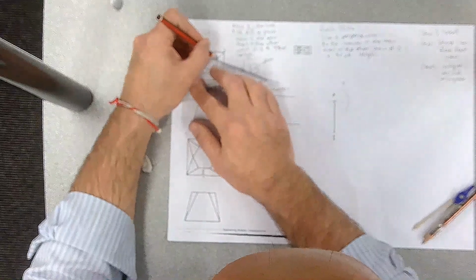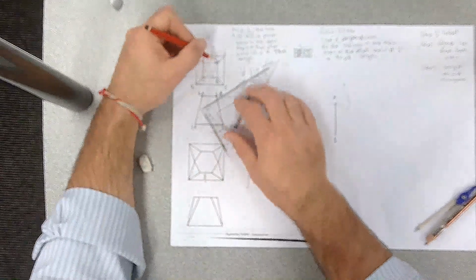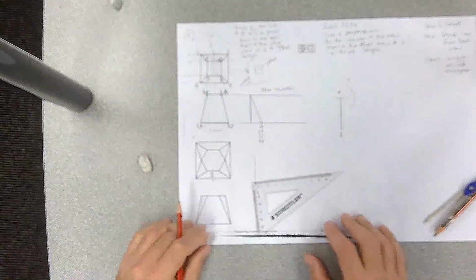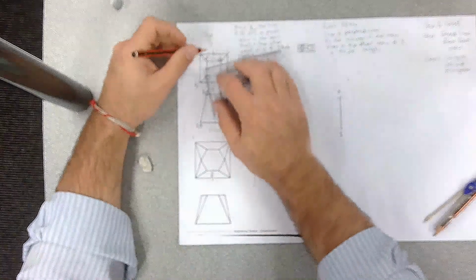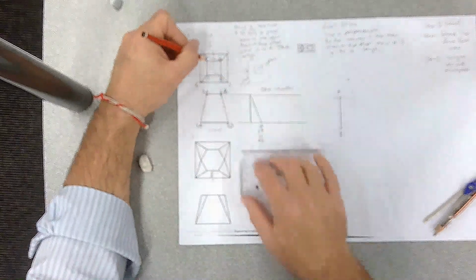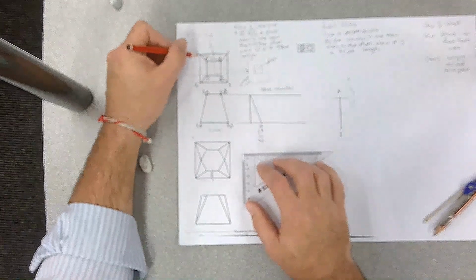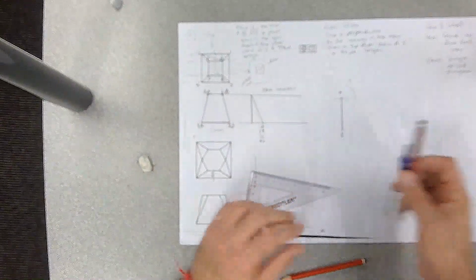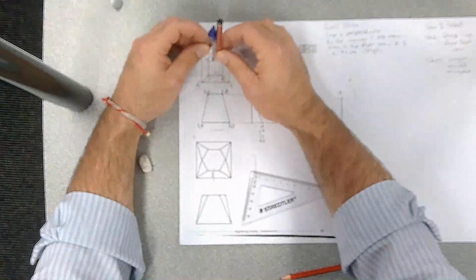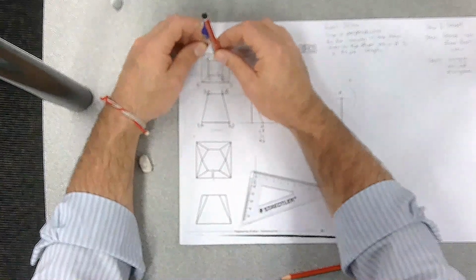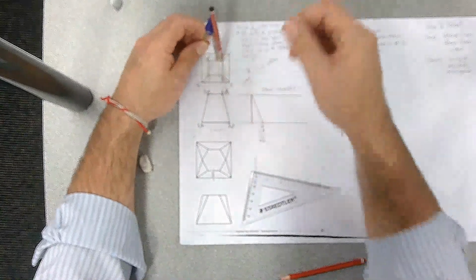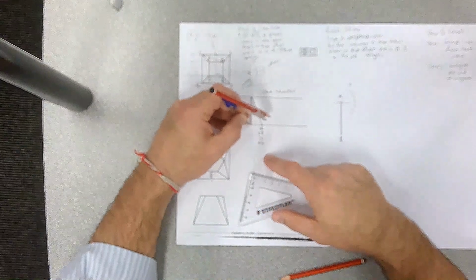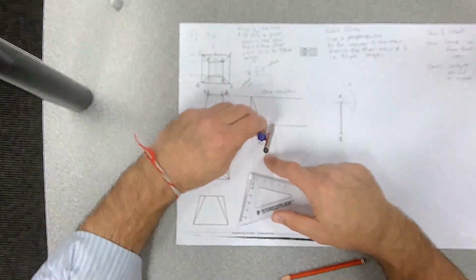So we're going to find the length of the line 1B. Now, because this is a symmetrical shape, any of the triangle lines in this shape are going to be the same length. Okay, so 1B, 2A, 4A, 1D. So once you find one of them, you're going to know all of them. And what we do is, it's the top view. So we've triangulated the face in the top view. We get a length, just like we did when we found this length here. And we swing an arc to find our true length.